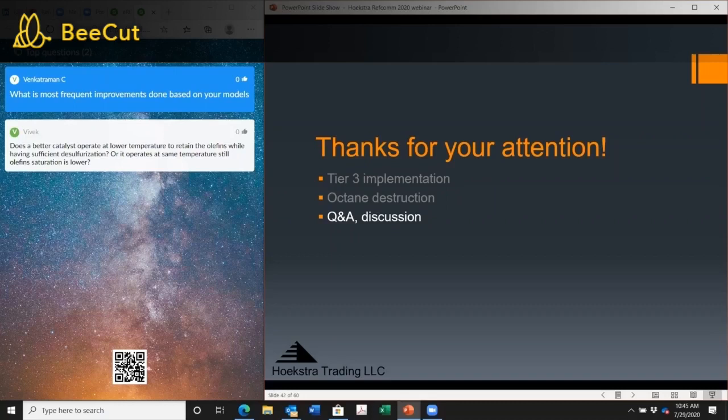Hi, George. I would like to add that we would like to retain aromatics because they have a very big contribution to the RON. For the conditions that exist in these naphtha HDS units, we have zero aromatic saturation, and we would like to retain maximum aromatics to preserve the RON. Right. I agree. They have a huge benefit there to the octane.